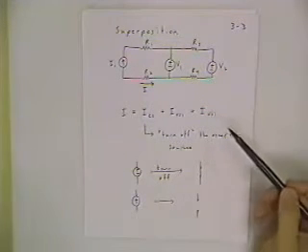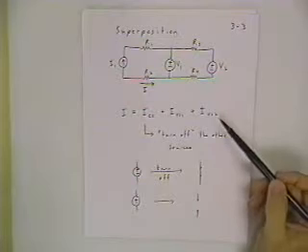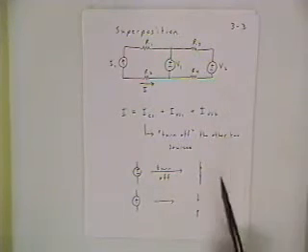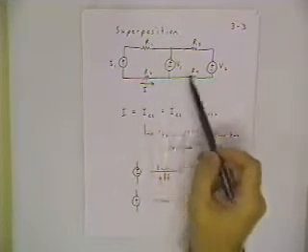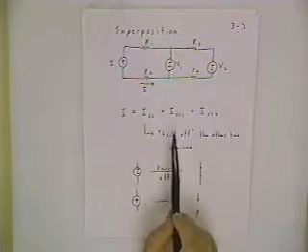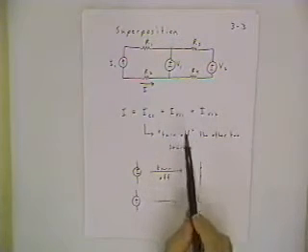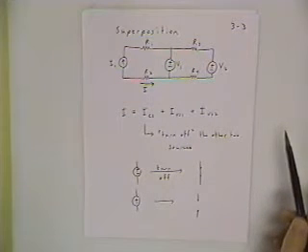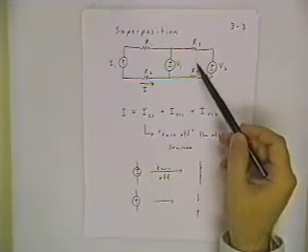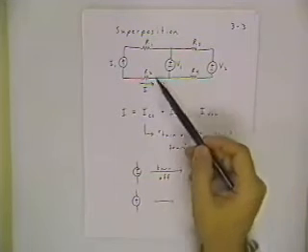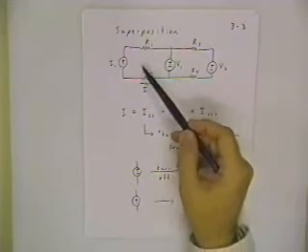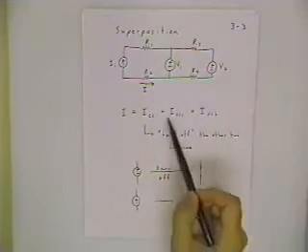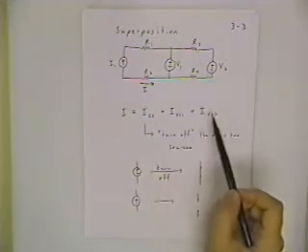But I don't even want to show you an example of this for the following reason. I just showed you an example where a circuit with essentially this same topology was solved with a single equation for a single unknown using the node voltage technique. If I wanted to use superposition to solve this problem, I would have to set up, in general, 3 separate equations, calculate 3 separate currents, and then add them up.